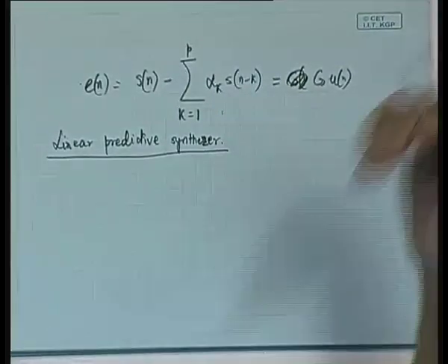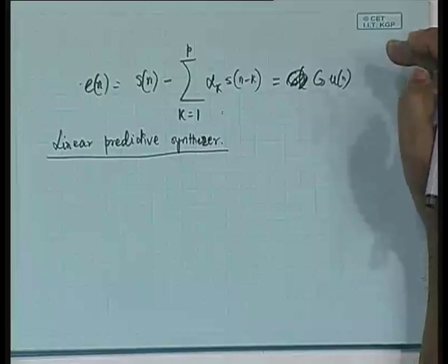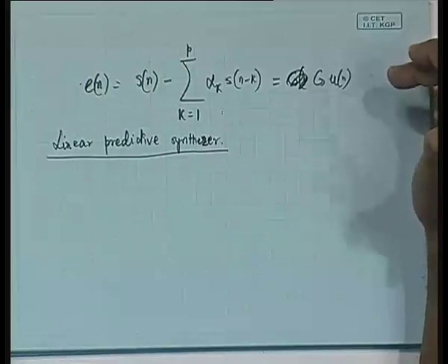So definitely, when we discussed the lattice formulation, the doubt was whether the K_i's would lead to some extra computational burden, and that would nullify the advantage of the lattice structure. It is not so. The K_i's can be computed in the lattice structure itself, and in fact the advantage we get in the lattice formulation is that no explicit computation of the correlations is required. One can just keep on recursively computing the error signals, and that itself would lead to the K_i's, and the K_i's would ultimately lead to the predictions.